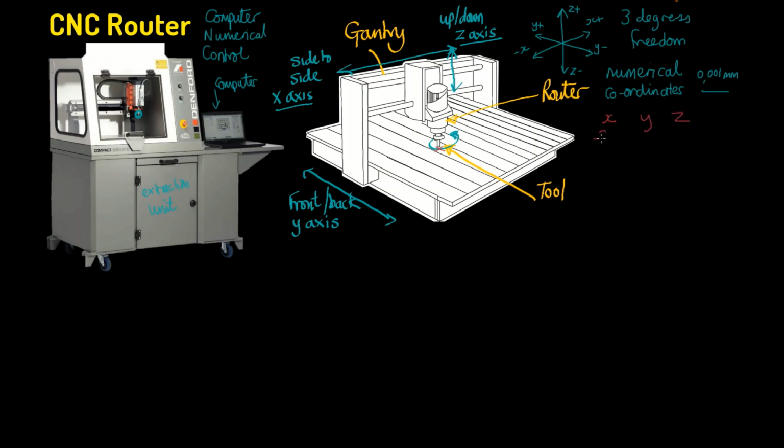So we could have moved 342 millimeters one way. We could have moved forward with the Y, so that would be a minus of, say, 260. And then the Z may be coming down ready to cut your material. Maybe we've gone down minus 10 millimeters there.